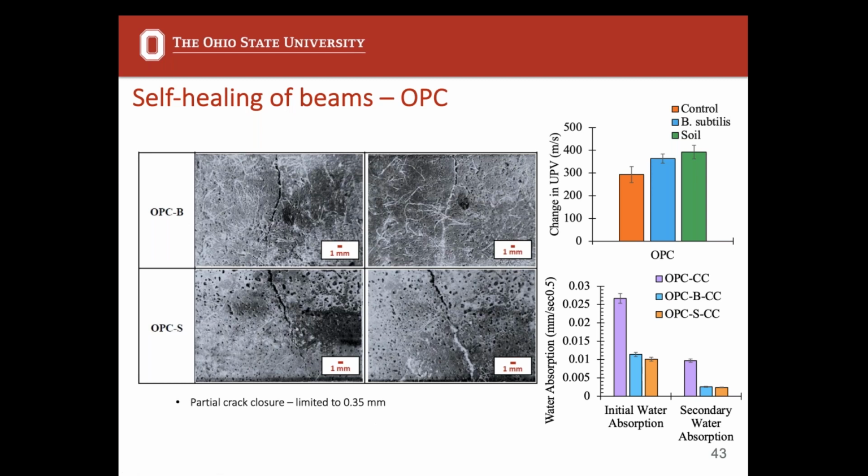So if you have a fiber reinforced system that's going to hold those cracks together, or if you catch the cracking at very early ages, it seems that this bacteria concrete is able to heal that crack and fill it with calcium carbonate material. Wider cracks are going to take a longer time to heal or may not heal. So up to 8 weeks, we didn't see full closure, but we did obtain partial closure of the samples.